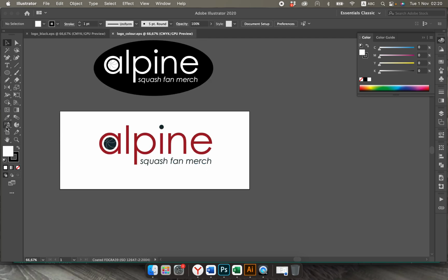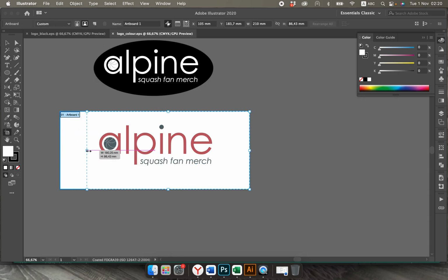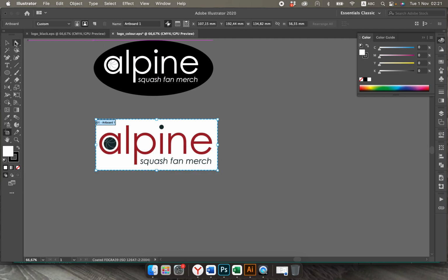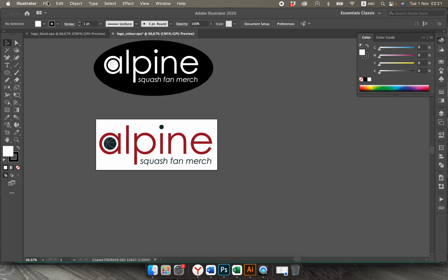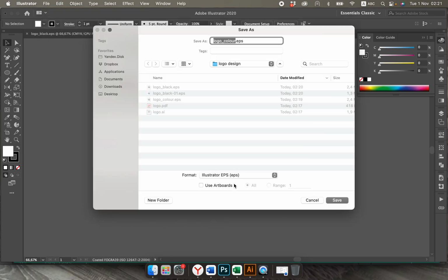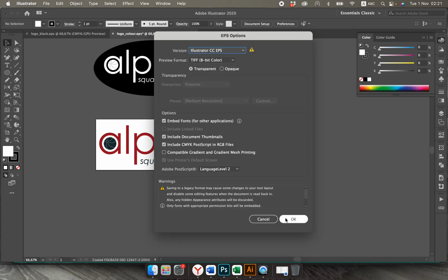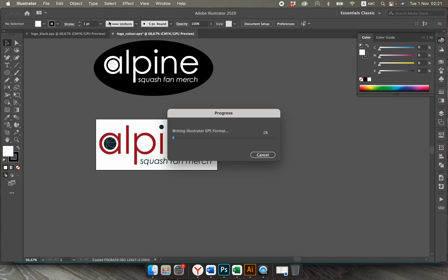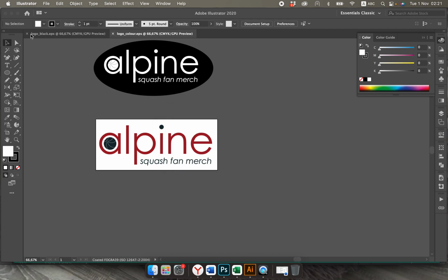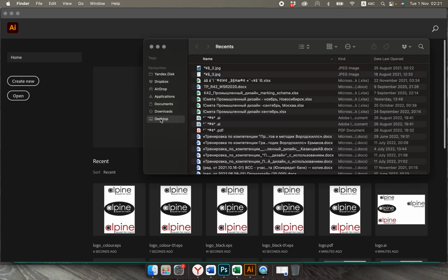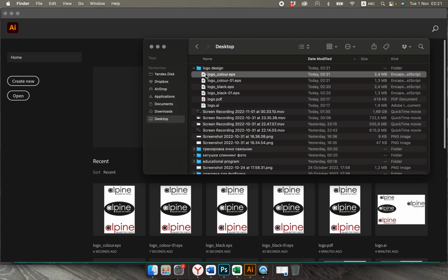Again, you just need to change the artboards, which is very close to your object. This helps you to use your logo in the future. So like that. And again, just go to File, Save As, choose the EPS, use artboards, logo colorful, save, replace. Okay, replace. And now, for example, if I open this EPS file, you will see that this EPS file is exactly about the artboards which I asked for.